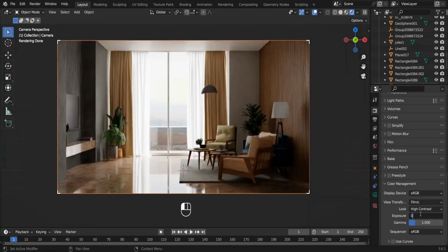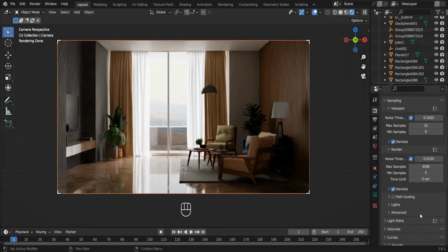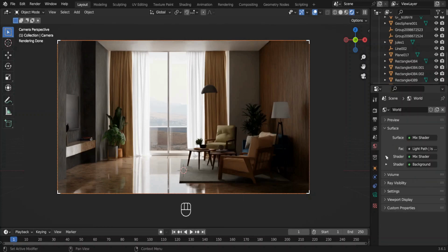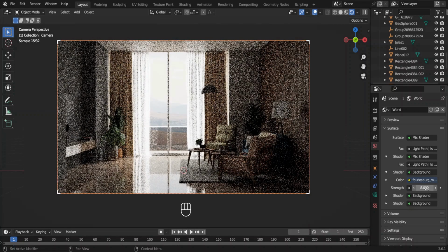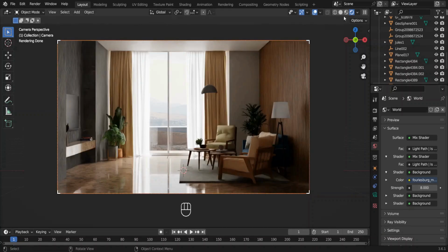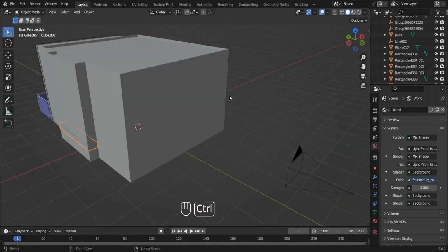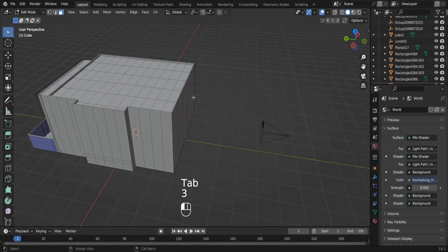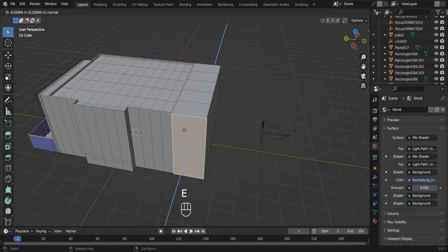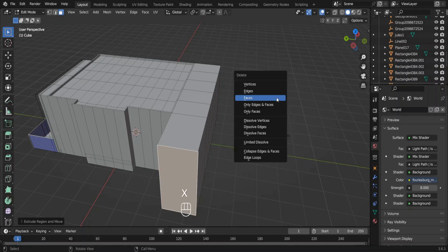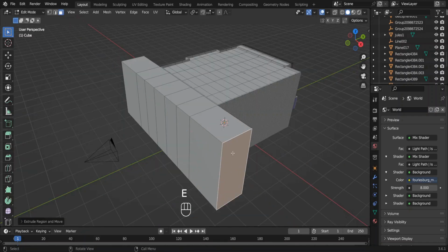Or the other thing we can do is keeping this exposure the same and increase the strength of the HDRI. We need to increase the strength of this shader. I'm going to increase that up to a value of 8. That looks a little bit better. Oh, there is this third way, which is my favorite. That is adding more doors and windows. Right now, our interior is a box without an entrance or an exit. If we can have two openings, like a corridor, like this, it would be much more realistic and we can even reduce the strength of the HDRIs.